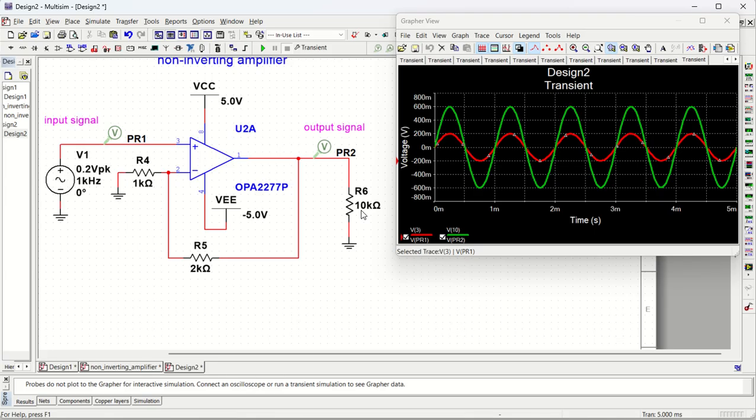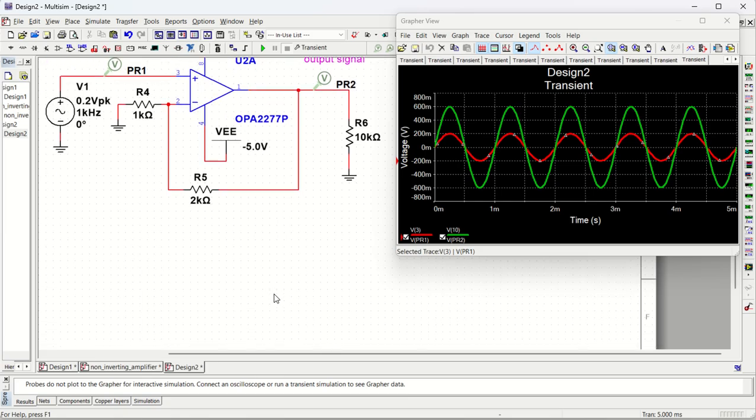If you want, you can give, you don't have to give this one actually. Okay, and then this is my input voltage that will be required to be amplified, and these are my sources. So if you want, you can have positive sources and negative sources both. If you have only input as positive, then you don't have to give negative sources, because op-amps are capable of running single ended supply. Okay, so let us do that.